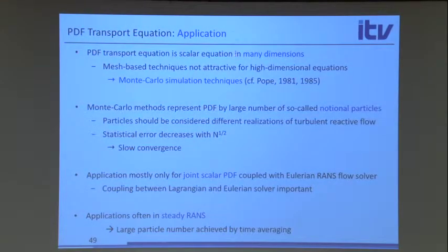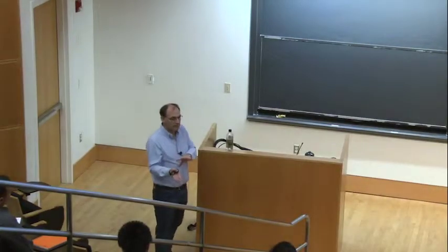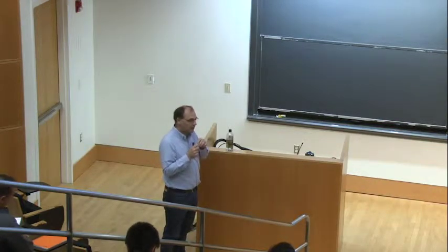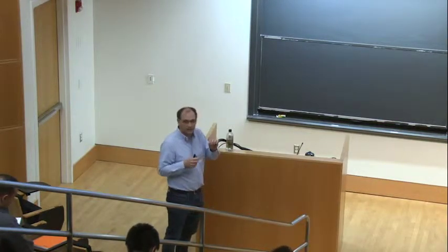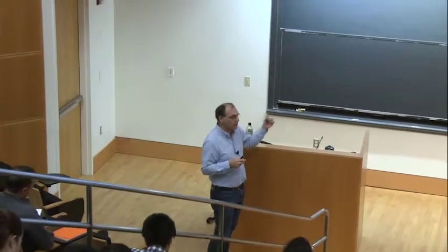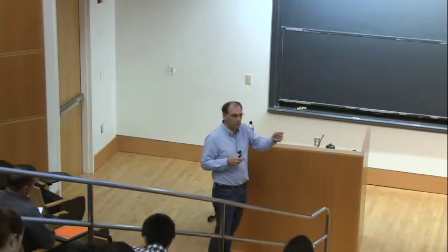people have developed techniques here that allow you to evaluate this. The technique that is used is the so-called Monte Carlo simulation technique. So rather than discretizing this equation, it is written in a totally different form with a set of stochastic differential equations, which are then solved for what's called notional particles.